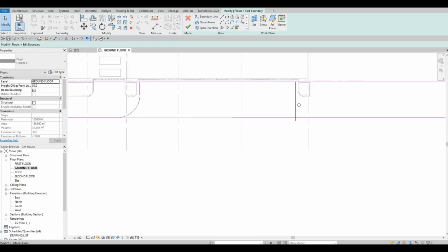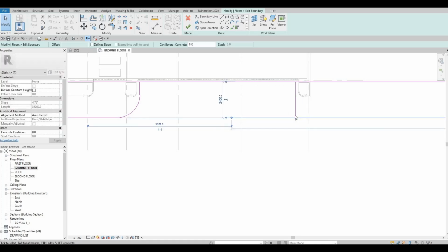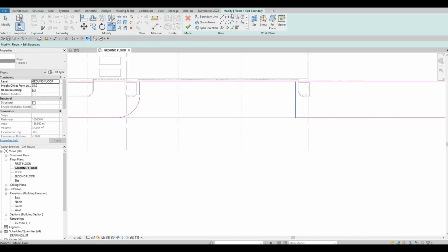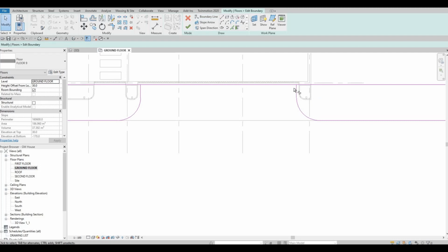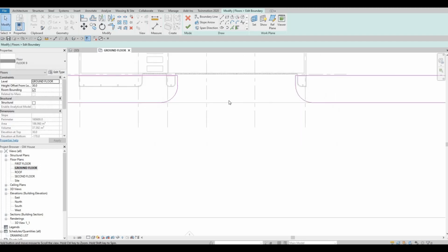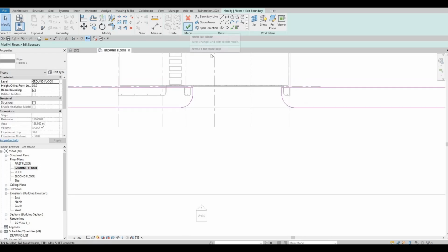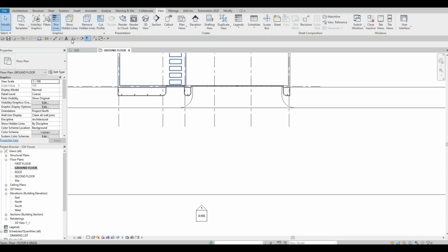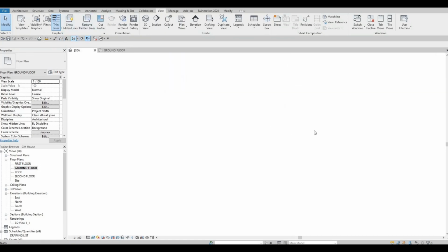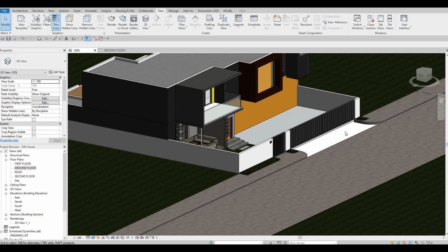For some reason it's not selecting for me to do it. So I'm gonna trim and extend first and then fillet it. There we go. 1500, and then now TR, trim and extend on all of this. So that's done right here, but this will have some gap. So if we double check again, there's going to be a gap there. So we just need to add the same material right there.